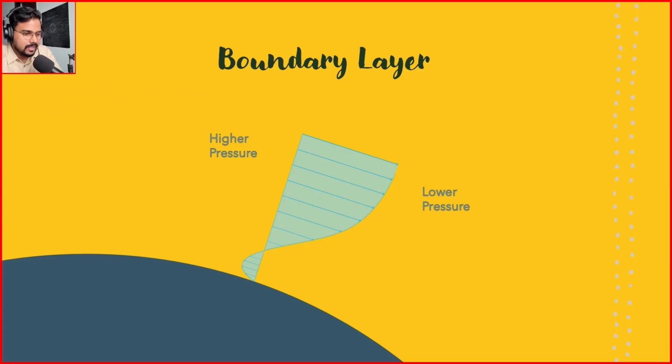That's the whole idea. Now, as we grow closer to the particular cylinder here, it becomes apparent that there is a higher pressure region getting created near the wall. This is happening exactly because as your fluid is moving away from the cylinder, the presence of static fluid is higher near the wall, whereas the presence of moving fluid is lesser near the wall at this particular location. Now, since that is occurring and we have a higher pressure region versus a lower pressure region, the flow tends to reverse its direction and we tend to see these eddies manifest themselves.